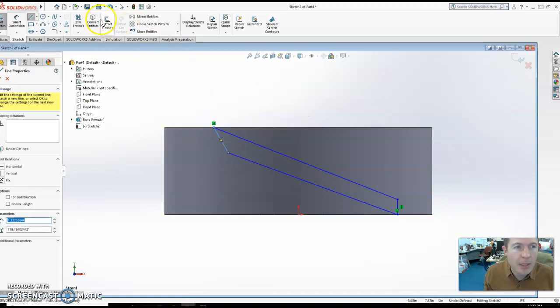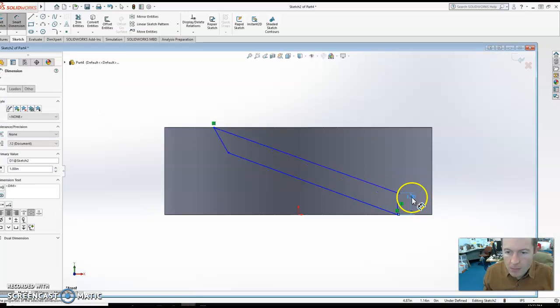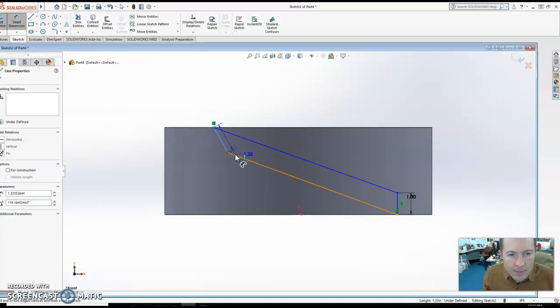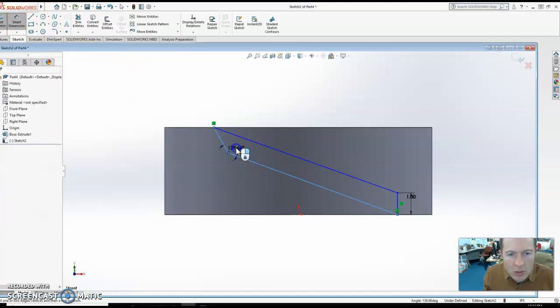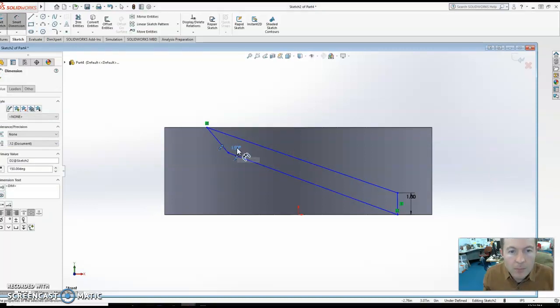All right, so here we have this blade. Let's set some dimensions on here. Let's say I want this piece for sure to be at least 1 inch tall. So that's 1 inch. Now another really important tool here, you can set angle constraints. So let me choose this one and this one. So there I chose those two. Now let's say I want that angle, I don't know, let's say 150 degrees. So there you see it extended that piece for me.